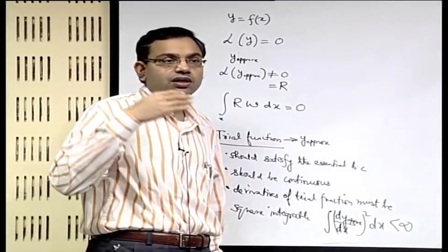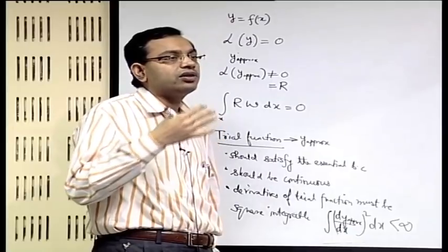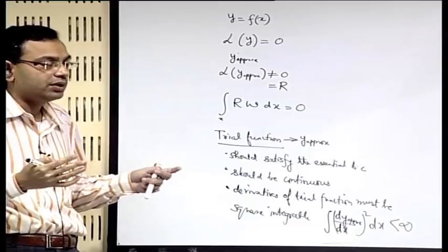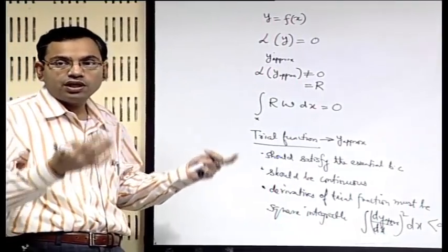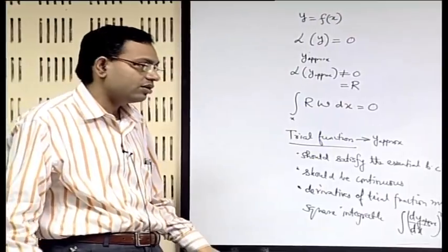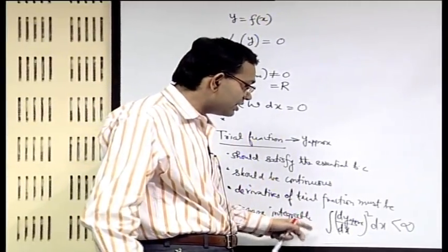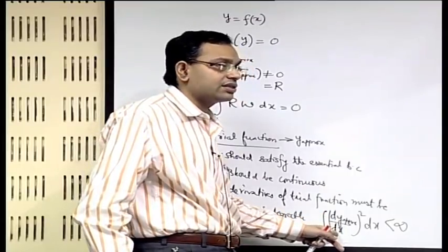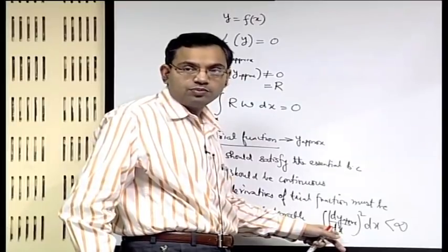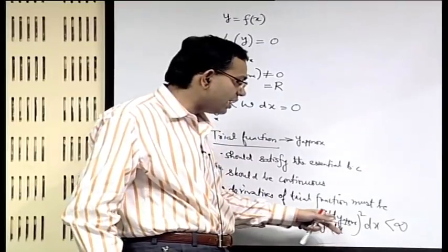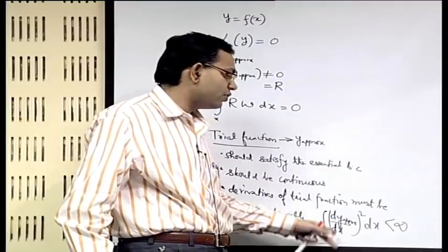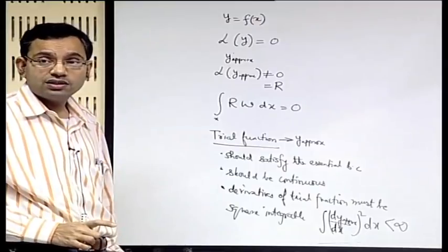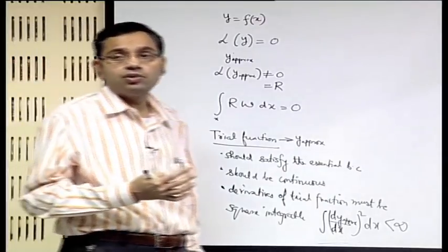So, the highest order derivative requirement for satisfaction of the continuity is the first order derivative for a second order problem. Similarly, for a fourth order problem, it would be a second order derivative continuity requirement. So, if it is a second order problem, then you only require up to the dy dx type of term for your continuity requirement. You do not require any higher order derivative corresponding to your variational formulation. However, you will require that if you do not go through the variational formulation.